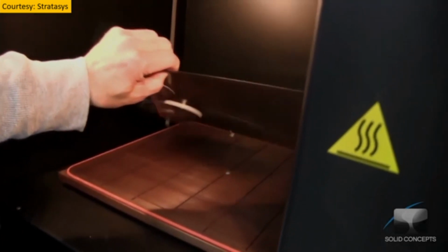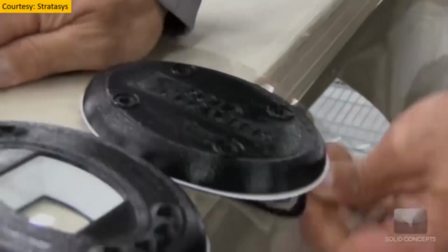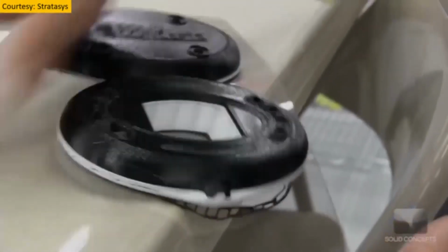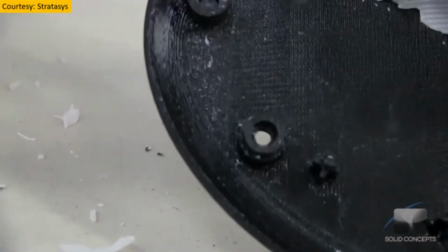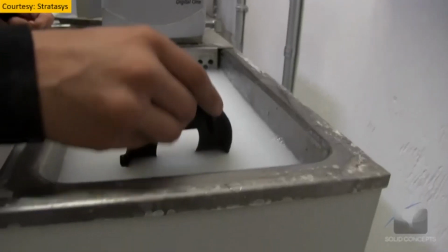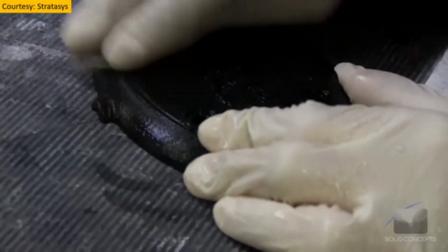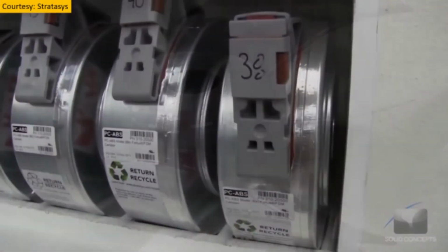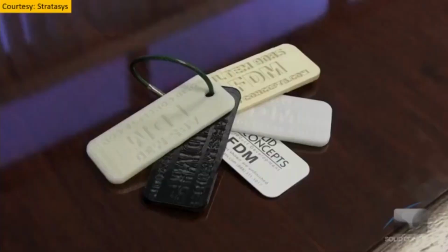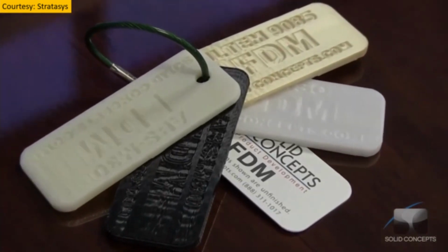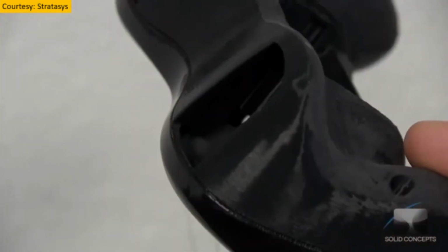The process repeats itself and builds the entire part, and then we take the substrate out and remove the part from the substrate easily. As much as possible, we remove the support by using mechanical tools, and later on we put the component into the waterworks where the support material is eaten away. After that we give a finishing touch to the final part, such as grinding and some chemical processes, and create the final finished part.